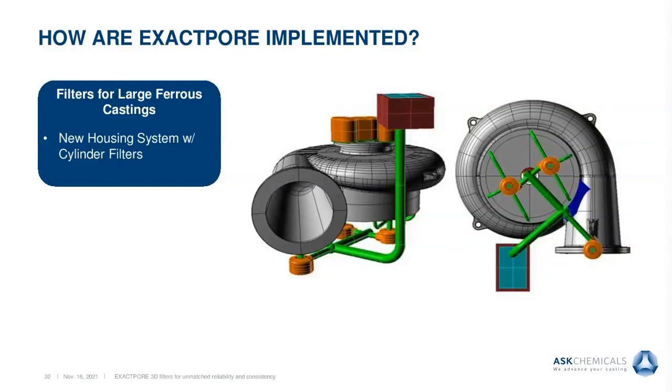When using an Exact Fill housing system, the filters can be placed at the bottom of the contacts, allowing a pressure drop that backs up the runner system and reduces any reoxidation potential due to the acceleration of gravity. The runner system remains full, the alloy is filtered effectively with the filters, and laminar flow is created at the base of the contacts.